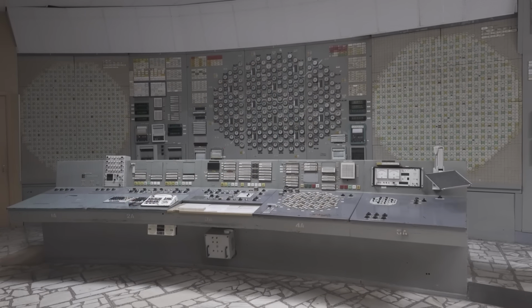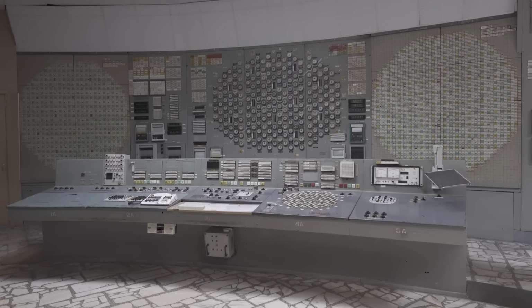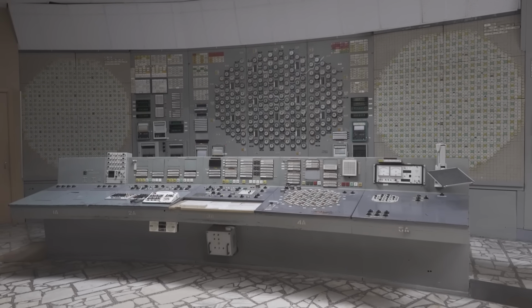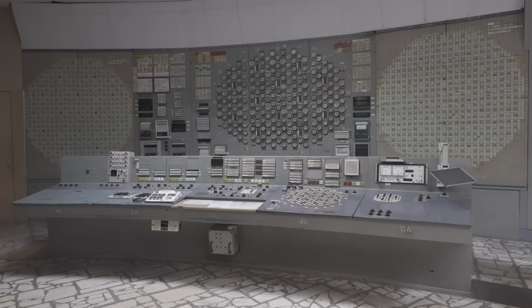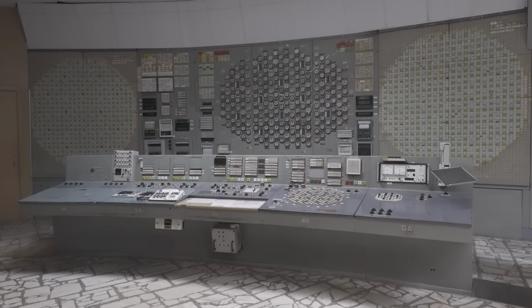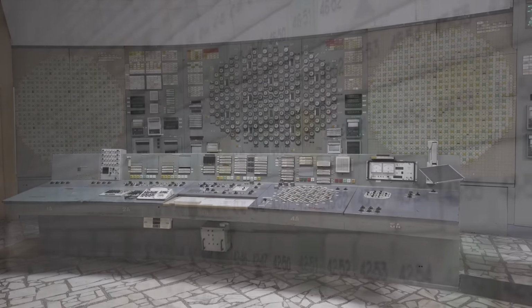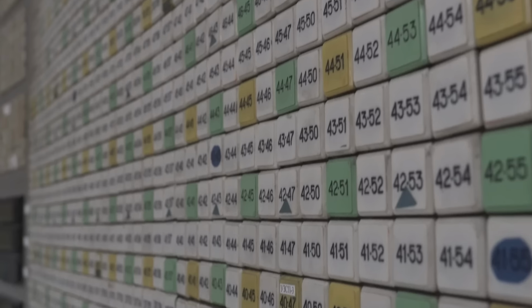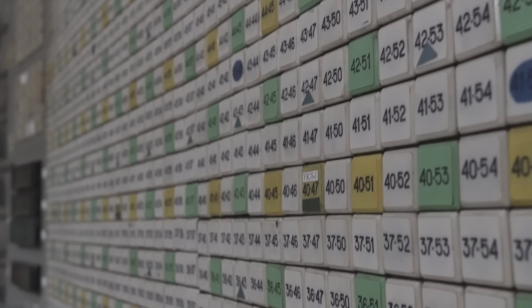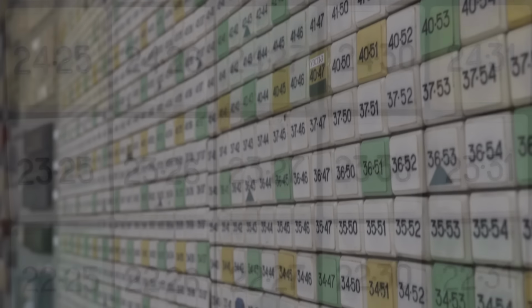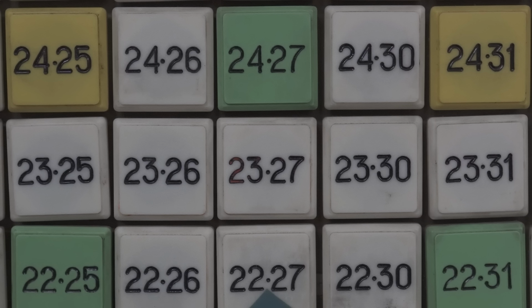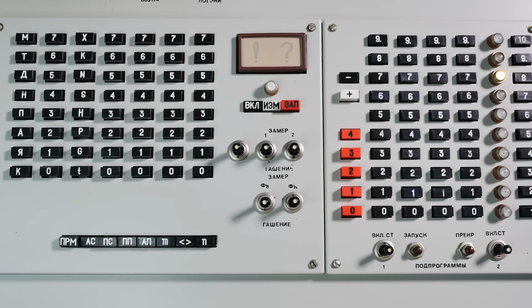Now, there are more functions. For example, you can compare some parameter of the channel with a chosen number and show all the channels where the parameter is higher or lower than your input. So, for instance, you remember that the absolute maximum of power for a single channel is 3 MW, and during normal operation it must not exceed 2.93. Now let's imagine I want to see all channels where power is very close to that.